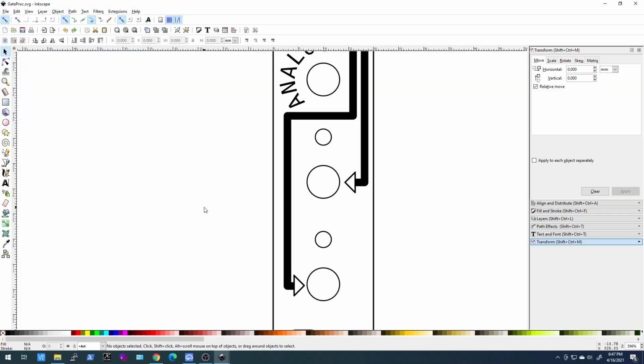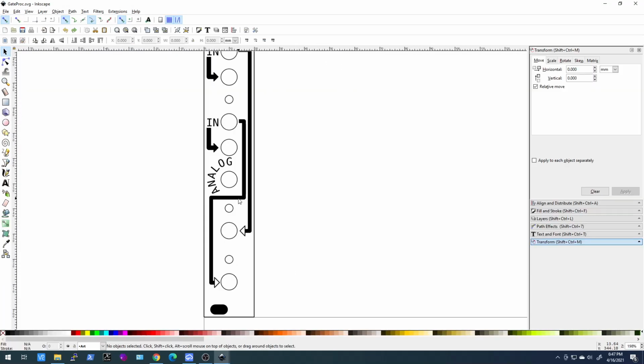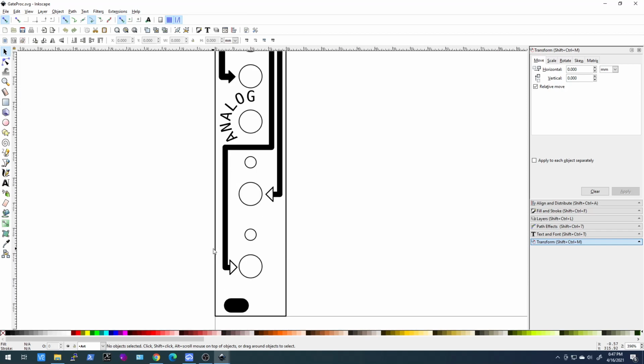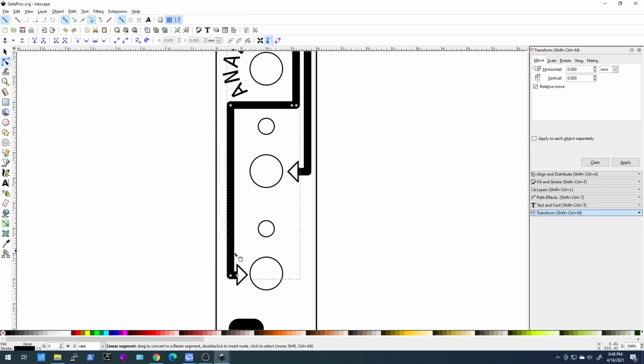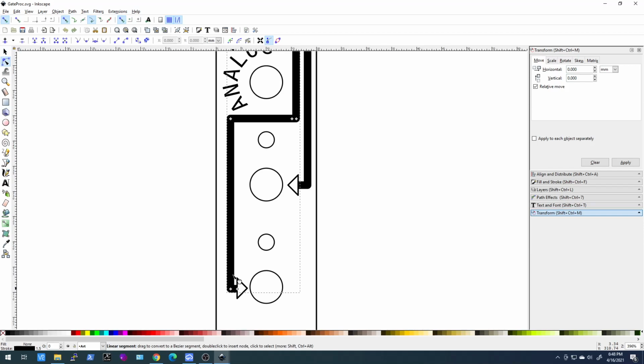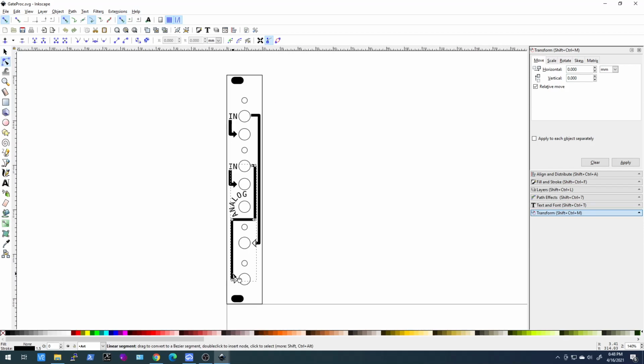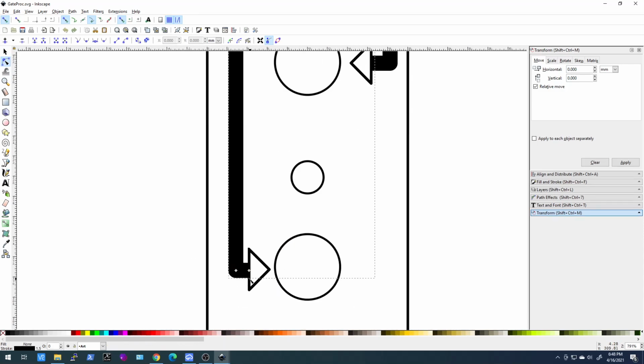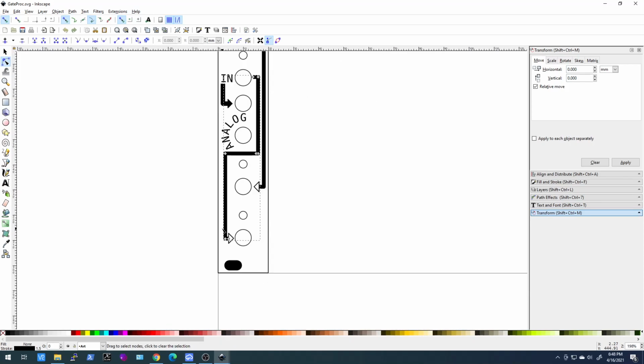And it's opening. So here's an example of a panel design for this panel that I created, and you'll see the shapes that I used have all been changed into, well, actually this one hasn't, so this is a good example. Let me show you what happens when I import this into EasyEDA. Remember I said that you need nodes at each of these corners, right? And right now the nodes are just in the center. So let me show you what happens. This is a good example.